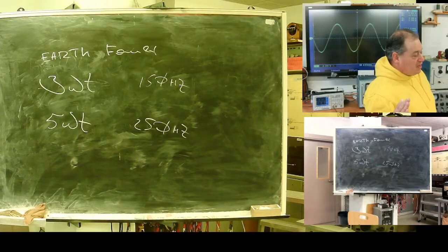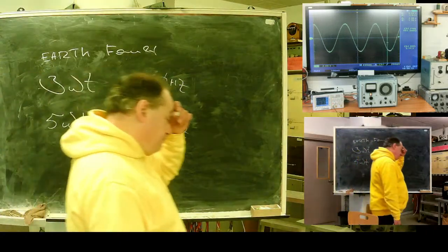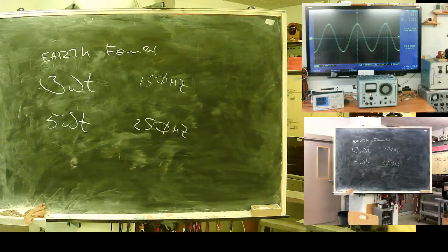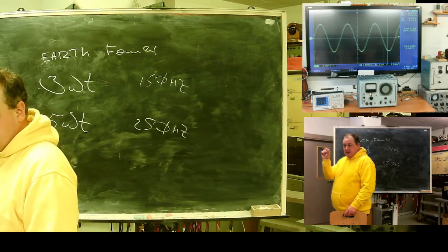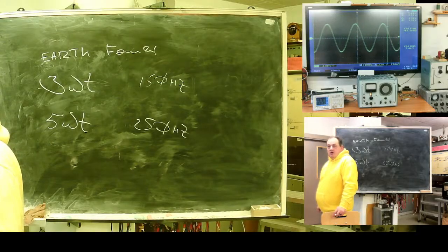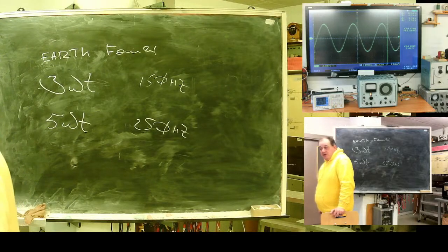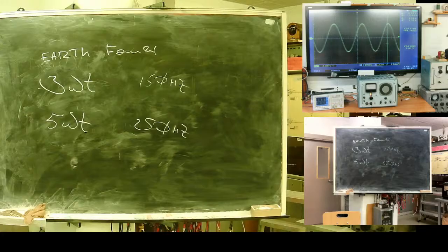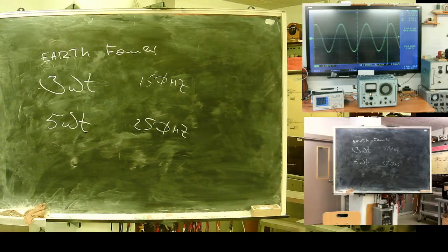On the other hand, where should the cut off line in analog preprocessing be? For example, if this device has a sampling rate of 1 kilohertz, a sampling interval of 1 millisecond, the signal at input should not contain components with frequency above 500 Hz. It's a must. The preprocessing part should cut everything with frequency above 500 Hz, or something bad may happen.